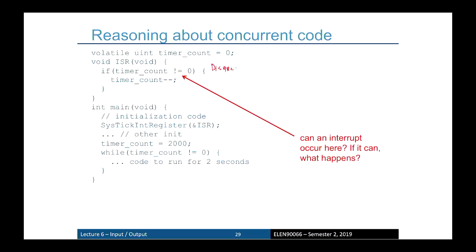And this sometimes is actually built into the hardware. Sometimes the hardware itself disables interrupts as soon as one occurs. It automatically does it for you, because it's a hardware thing. You've got to catch it straight away. Software's too slow to catch things. So you disable interrupts, allow it to process, and when you finish the service routine, you then enable them again.